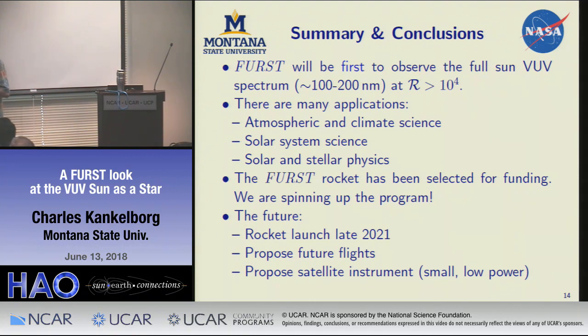And ultimately, what I would really like to do is squeeze this thing somehow into like a 6U CubeSat, which sounds really hard, and it sort of is. We've got presently a 1 meter Rowland circle in our design. That's obviously not going to fit in this area. A 6U CubeSat is this big, right? 12 inches by 8 by 4. So how will we do that? I think the keys will be a detector with very small pitch, very small pixels, not 12 microns, but maybe 4 or something like that.